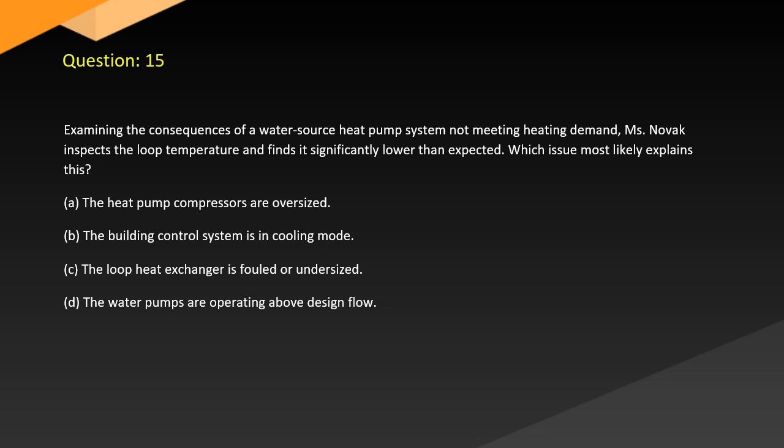A. The heat pump compressors are oversized. B. The building control system is in cooling mode. C. The loop heat exchanger is fouled or undersized. D. The water pumps are operating above design flow.